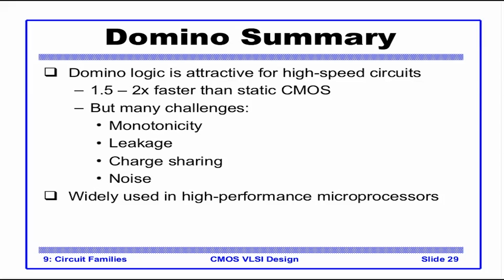Static CMOS is very robust. It doesn't need a clock except for sequential elements, the noise margins are very high, and it's reasonably fast. That is why it is more popular.